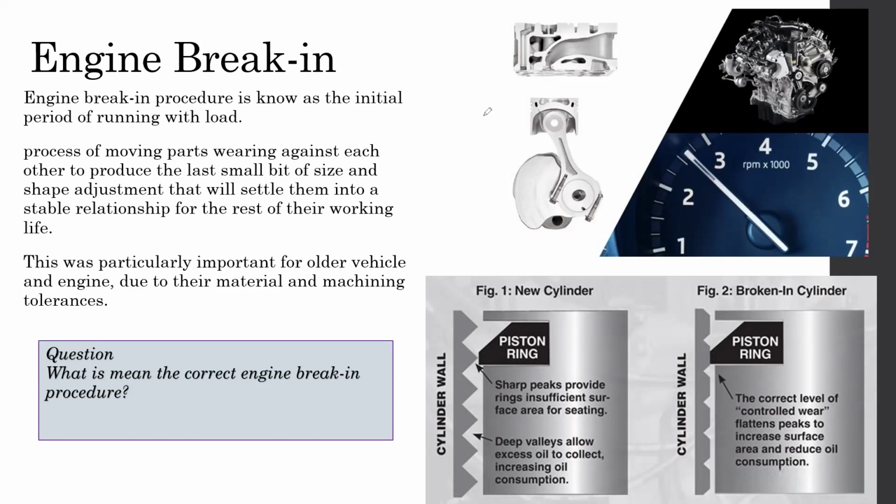Even though that is done, the exact cylinder wall roughness is not matched by the machining process alone. In order to match it, the engine has to be heated up to operating conditions and run for a certain amount of time. While the piston moves up and down, it removes a very thin, microscopic amount of material.